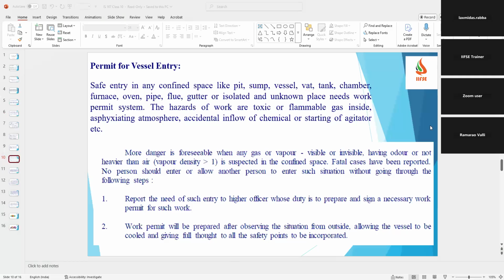If any two or three of these meet the criteria, you can declare it a confined space. And also, most organizations, whenever there are any entries, vessels or tanks, will define that a confined space permit is required, and without a permit nobody is supposed to enter.